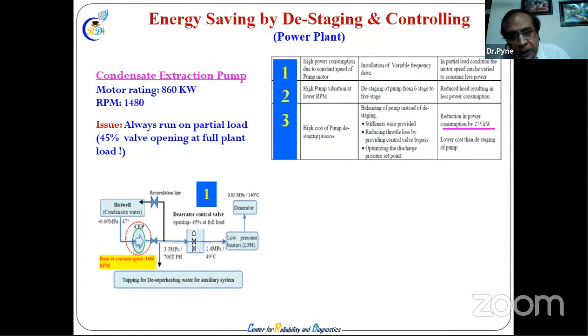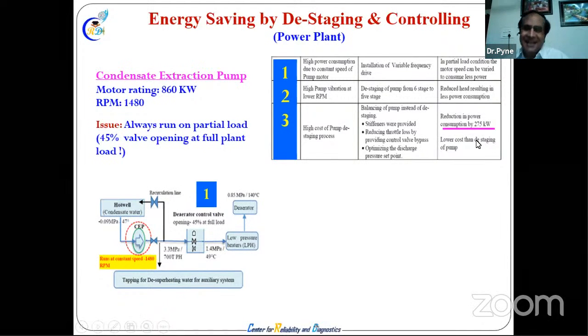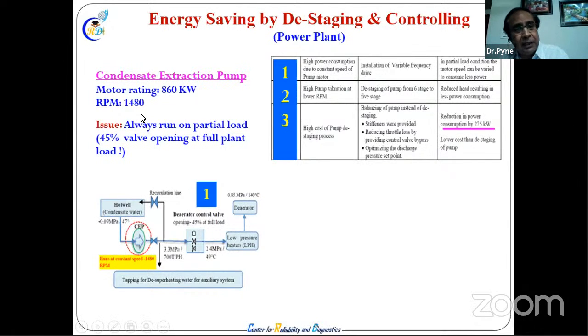And the 5 stage pump also had a problem. So accordingly they made some changes in the structural plates and other things and material, all the things they've done. So in the different cases, in 2-3 stages they got the benefit, and that benefit was 275 kilowatt. This benefit, on a lighter side, is the cost of not selecting the right pump initially. So nothing to blame. They're getting this much less right now. Otherwise, they would use this machine, and this machine would create so much energy loss, more than 50% energy loss. So they've got this gain.